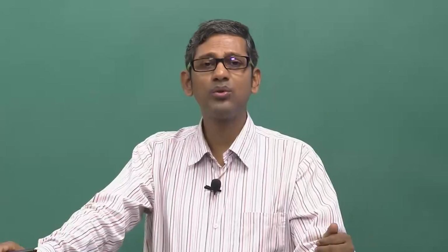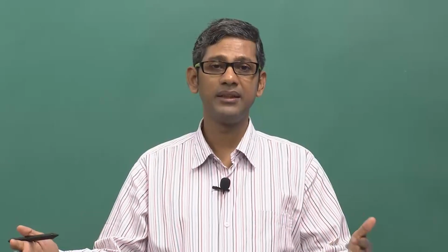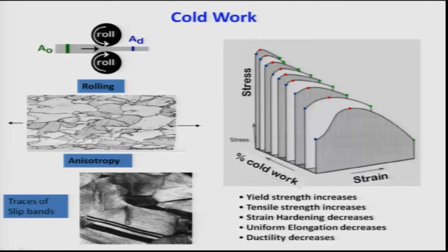So, that is why all these cold worked or warm worked materials are subsequently annealed, or heated to temperatures, so that these defect structures can be annealed out or rather organized properly, and that is what happens in recovery, recrystallization and grain growth. These techniques, this class of phase transformations, deal with how to control the defect organization inside a cold worked or warm worked material.